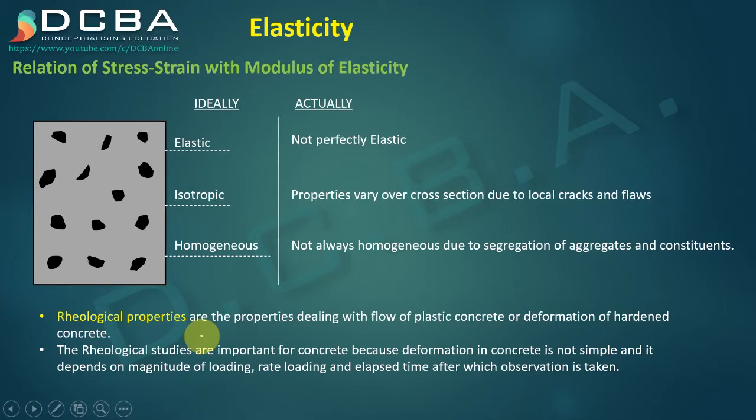These rheological studies are very important for concrete, because deformation of concrete is not simple, and it depends on the magnitude of loading, rate of loading, and elapsed time after which observation is taken. Magnitude of loading means how heavy the load is that we are putting on the concrete. So definitely the deformation of concrete is going to depend on how much load we are putting on the concrete. Second is the rate of loading.